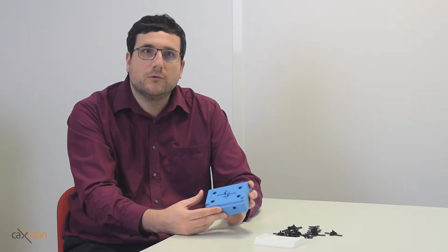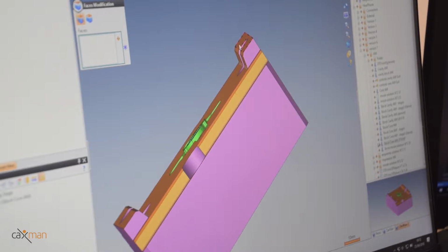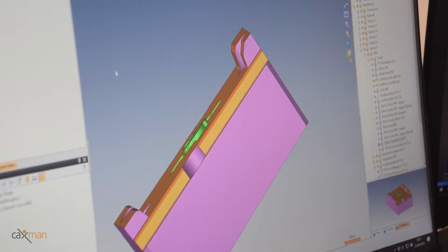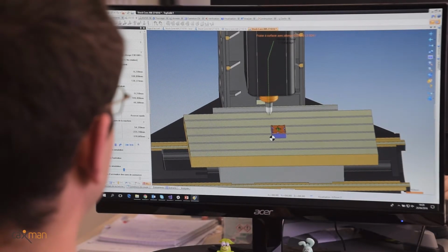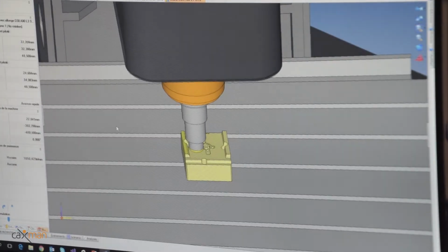It is important to understand that the quality of the surfaces produced by printing is not perfect, and we must therefore do machining on the operational areas of the part. These areas will be determined beforehand in a virtual model by adding a volume of material. This virtual model, which is then printed, becomes the raw material of the workpiece to be machined.